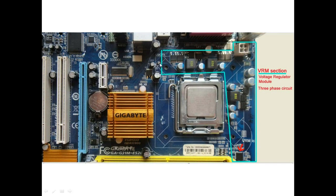And this section which is near to the CPU, we call it as a VRM section. VRM stands for voltage regulator module. The purpose of this section is to give out supply to the processor. This is a 12 volt connector, PS connector. The VRM section takes the 12 volts as the input and gives out a supply to the processor, which we call as the CPU core voltage.